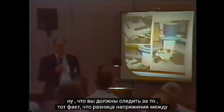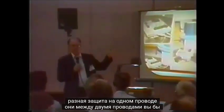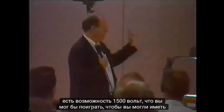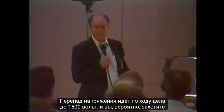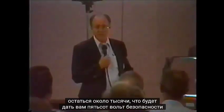Yes? What kind of wire are you using? Well, what you have to watch out for is the voltage difference between 2 wires. So if there's 750 volts on one wire there, between the 2 wires you would have 1,500 volts possibility that you could play with, so that you could have a differential of voltage as you go up of 1,500 volts, and you'd probably want to stay at about 1,000, which would give you a 500 volt safety factor.